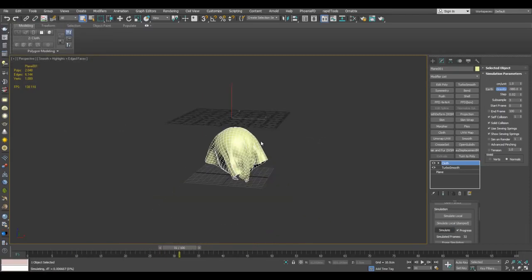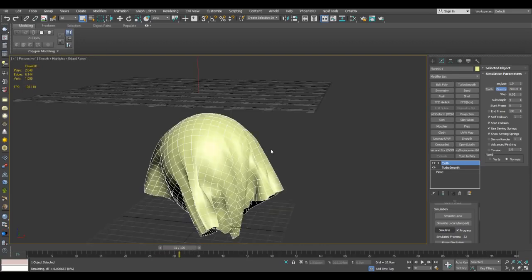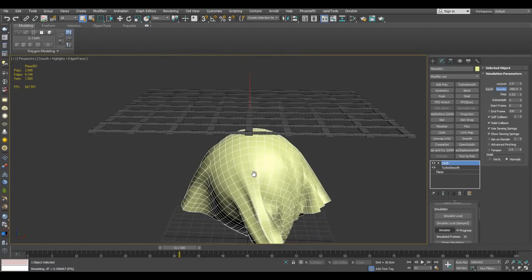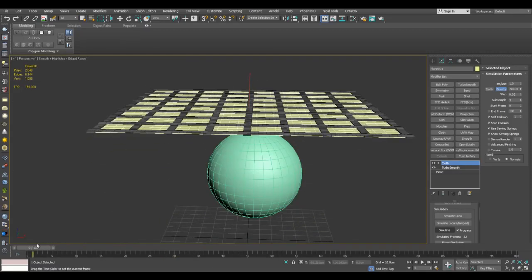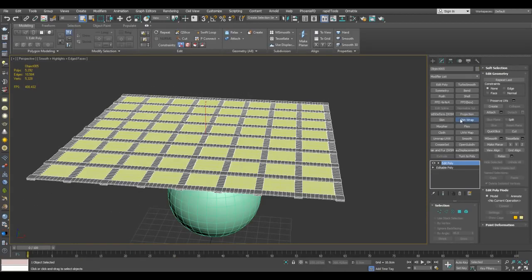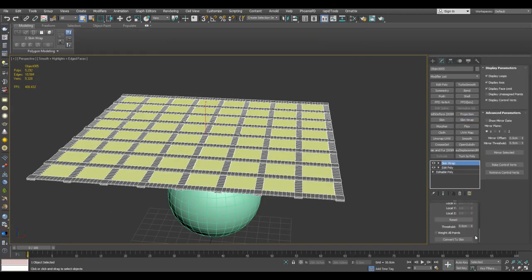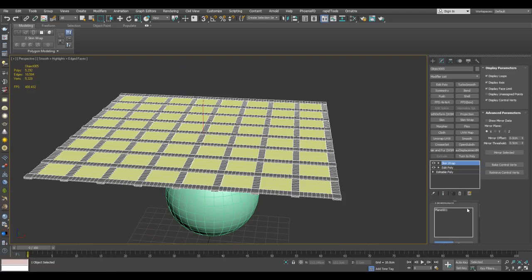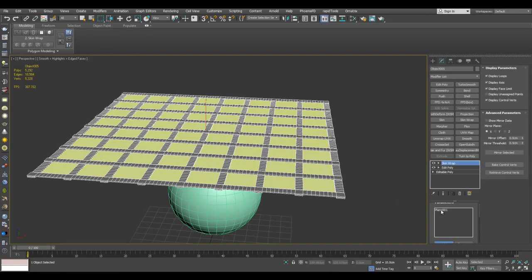As you can see, that's been less than 10 seconds. So number one, this technique works a lot faster because we're dealing with a much simpler mesh here. So now what I would do is go back to frame 0, select the net and skin wrap, scroll down, weight all points, and for deformation engine, it may be better to switch this to face deformation, and then add the cloth object. Be sure to give your objects more descriptive names so it'll be easier to select them.